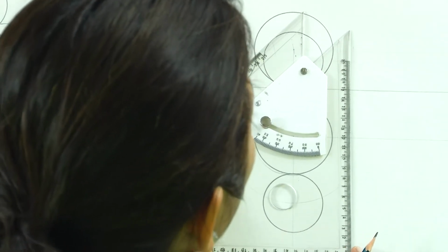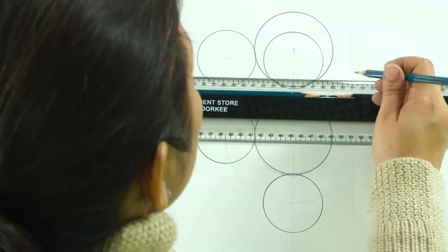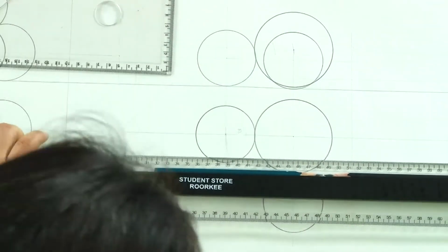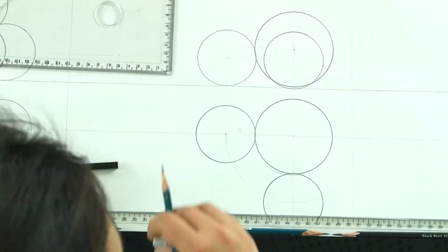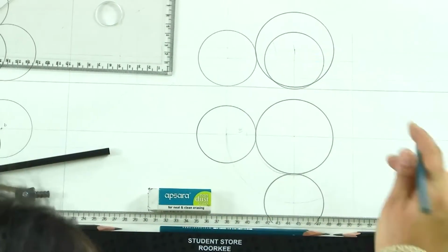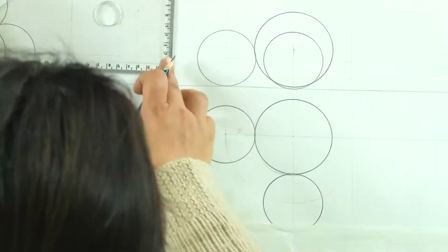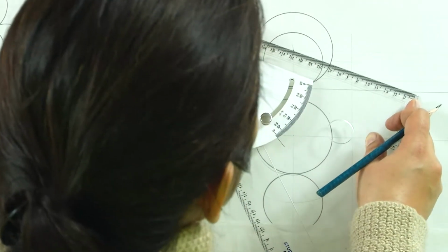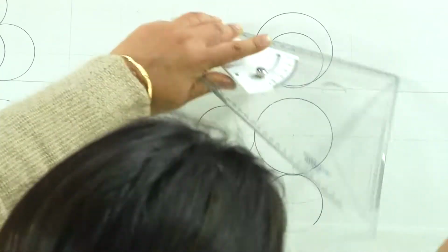It is again on the same line. So, what will we do? We will have this line passing through at a height of 1 centimeter from the ground. But since we know that all these three spheres are falling on the same line which is parallel to VP, we know that this will be somewhere here. Now, the radius of this bigger sphere is 4 centimeters plus 1, 5 centimeters.